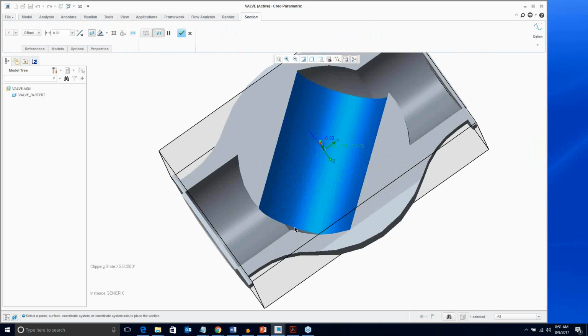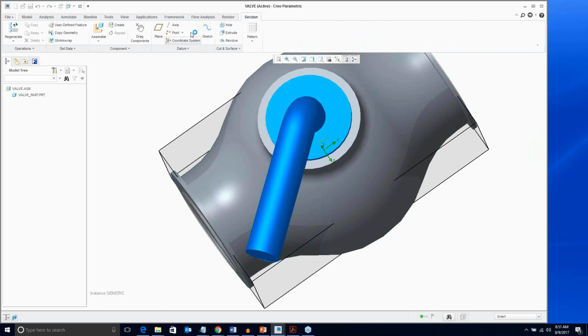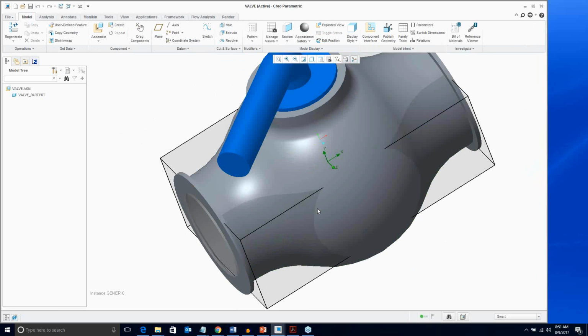And the challenge is to understand what the pressure loss is just across this ball valve due to it being turned by X degrees, right? How much pressure are we losing? Or what's our hydraulic loss across this valve, right? And so I'll close out of this cross section here.